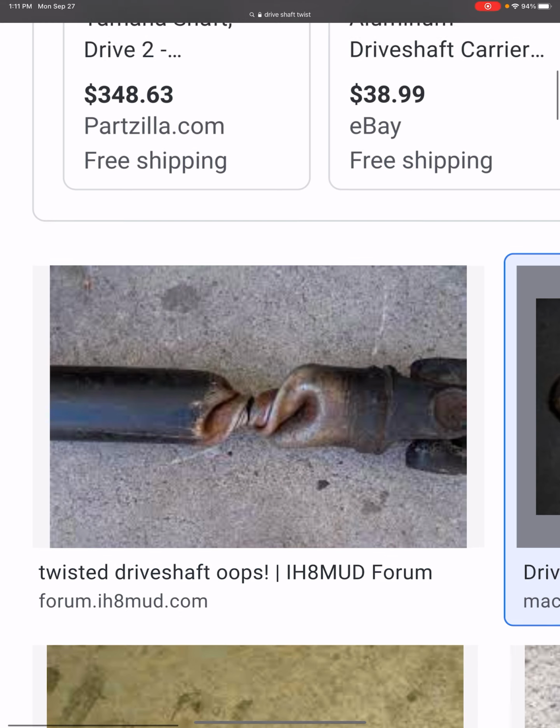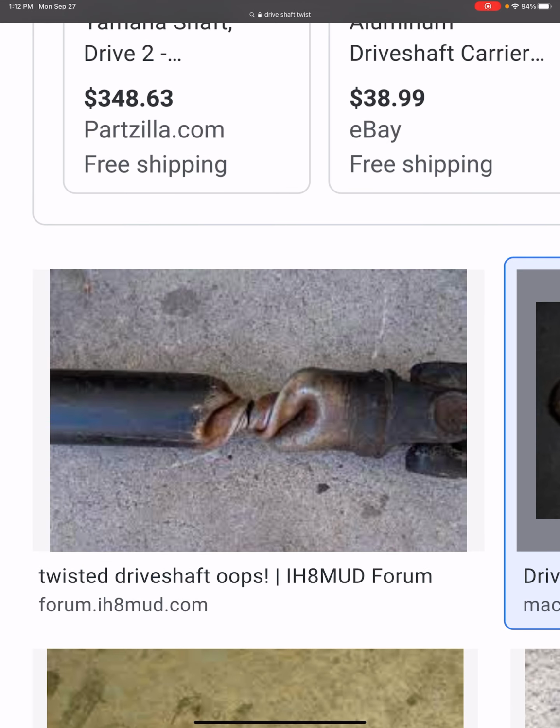That one's better. That's a drive shaft that's failed due to excessive torsion, okay, or torque, right? This didn't fail due to yielding, it failed because of buckling. And we're going to get into more of this, you're going to realize that at a given angle, even though we're trying to twist this, and you could imagine it being like two planes shearing one another, well, if you orient that same piece of material at an angle, you're really trying to pull the steel apart and actually push it together.